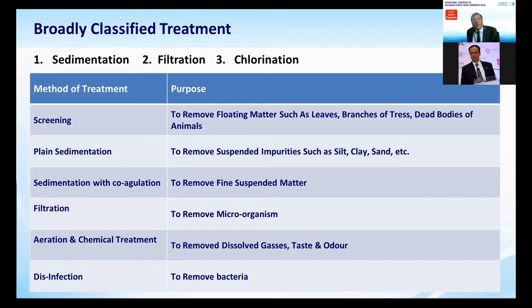This technique is very old, and now we have alternative advanced technologies. We can also go with ultrafiltration, a technique which requires far less area and far less time for setting up the project, and its reliability is higher than the conventional sedimentation system, because there you need to have proper dosing, jar testing, control of the parameters, sludge handling, and a lot of other things you have to manage to control the process.